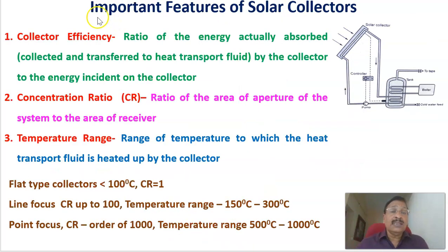Now let us see the important features of solar collectors. What are the parameters or specifications? Collector efficiency. Collector efficiency means the ratio of the energy actually absorbed or collected and transferred to the heat transport fluid by the collector to the energy incident on the collector. That ratio we call the collector efficiency.